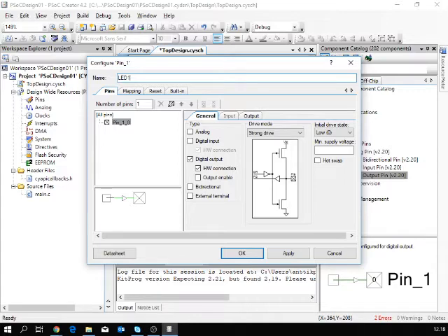This hardware connection would be something you could connect an internal block to, for example a PWM block output. But in our case I want a software controllable output, so I will click that one off. So this is just a digital output without internal hardware connection.